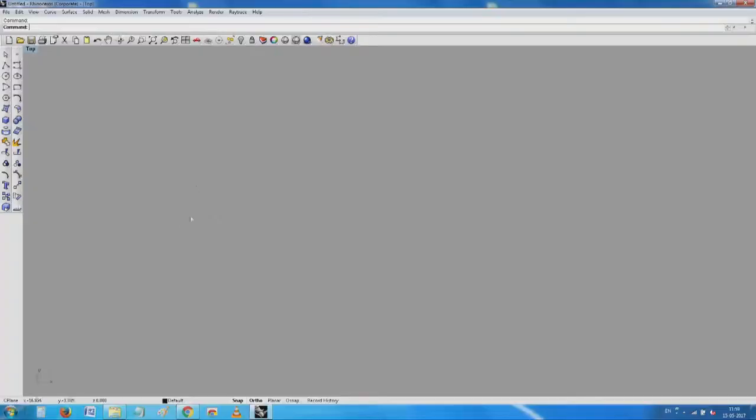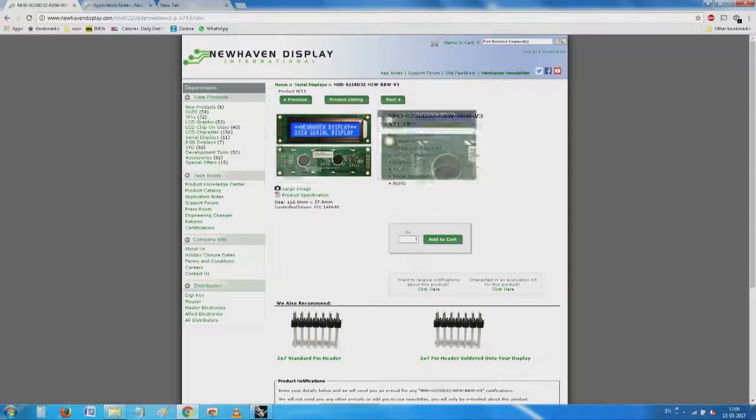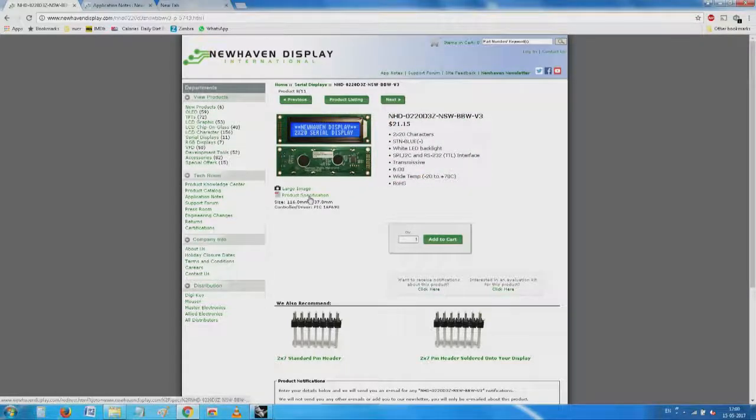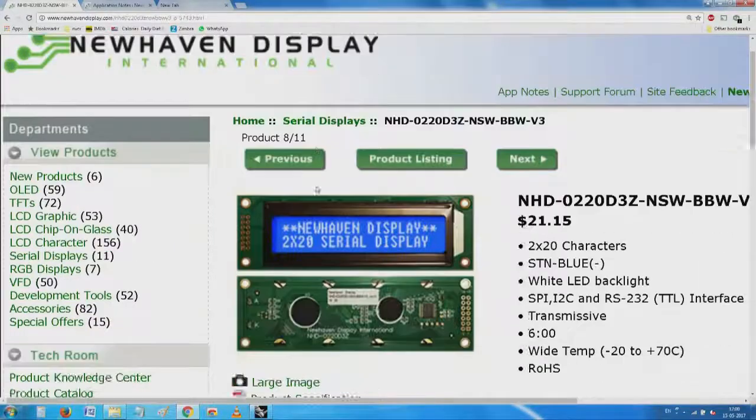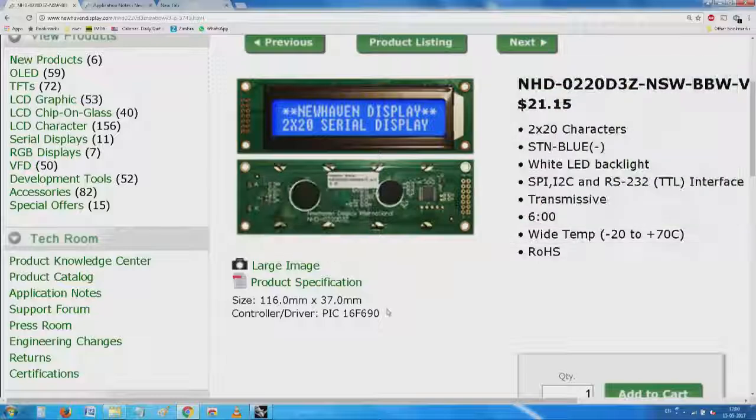As part of this, we may go and then after having run a breadboard test and then decide on the standard modules. In this case, if you see typically, the displays are this 20 characters wide 2-line displays, which seems to be typically what is used.